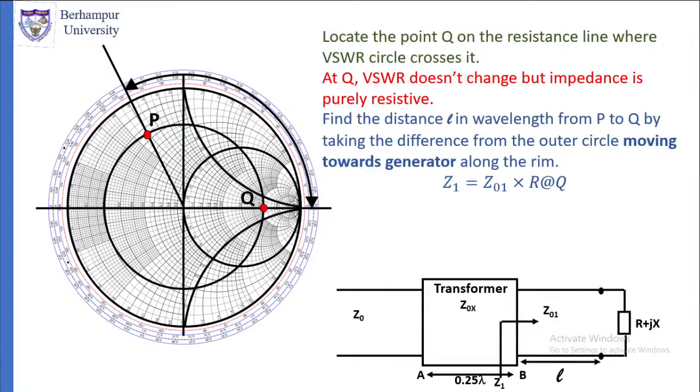At the two ends of the arc, at the point Q end, the wavelength is 0.25 lambda, because it starts from 0, goes to 0.25 after 180 degrees, then after 360 degrees it is 0.5 lambda, which is reset to 0.